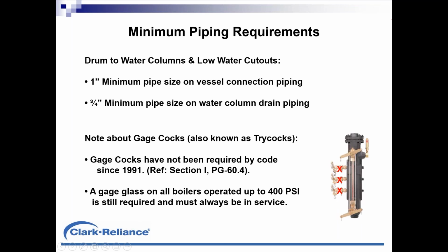When you open up the valves, they vent to atmosphere. There's a little nozzle on these, and my middle one is normal water level. So what would happen is open the top valve, you'll see a stream of steam, so to speak, or a plume of steam. When you get to the normal level or low level and you're in a water situation, it'll squirt out that nozzle, a stream of water, just like water out of a garden hose. Over time, this technology has faded in popularity.